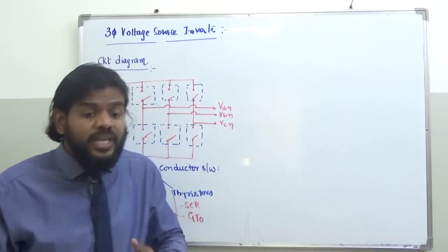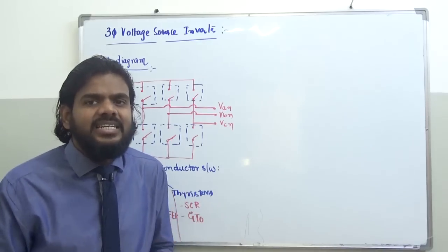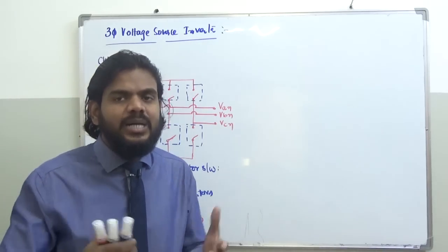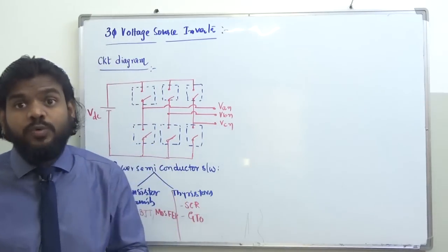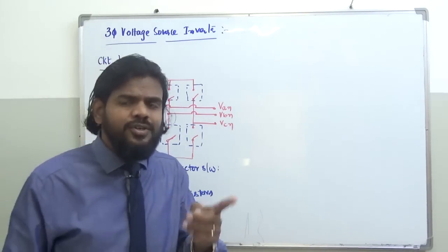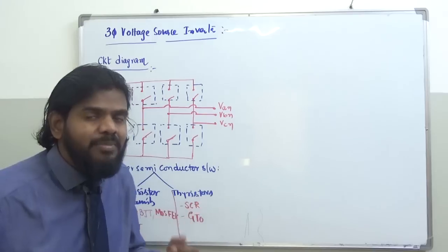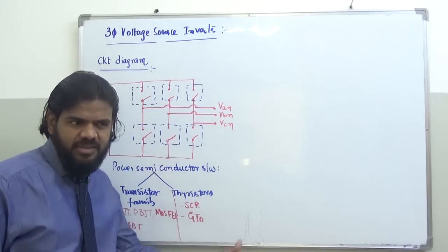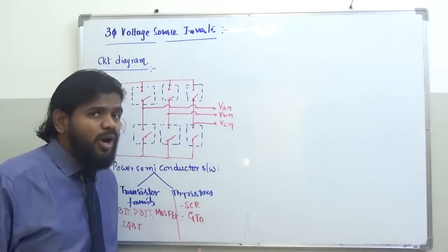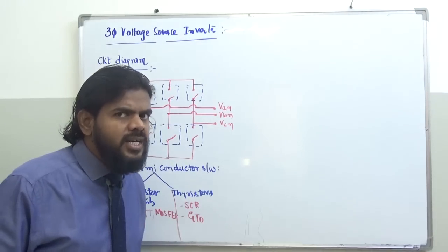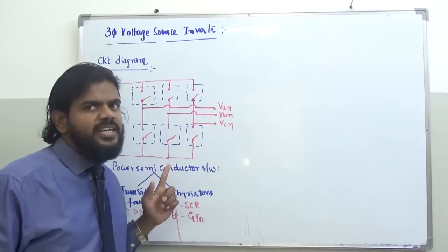So you need to take an additional arrangement, an auxiliary circuit, and those auxiliary circuits are called commutation circuits. The meaning of commutation is changeover from on to off and off to on. This is how you have a commutation circuit requirement when you use a power semiconductor device under the thyristor family. So it is not suggested to use this family of devices when you are taking up an inverter discussion.